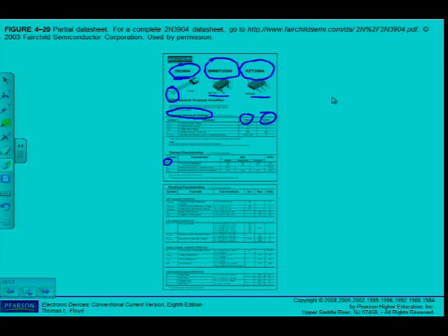As I can see there, power dissipation, which is total device dissipation, and then you will see there are three transistor names. It's the 2N3904, and the MMBT3904, and the PZT3904. And you will see that they have different power dissipations.